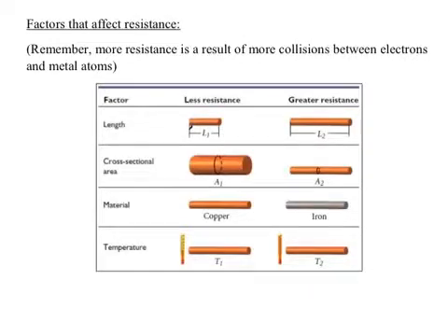It's like having 4 pipe drains coming into one in your house. You'd want the big pipe drain running out to the ground and all the other pipes to be smaller so that when they come together, they can actually flow out. Whereas if you had 10 pipes that are 1 or 2 inches each, and then an exit pipe that was only a 1 inch diameter, it's going to get all backed up. All your water's going to get backed up in your sink and your shower, and it's not going to flow out. So a larger pipe means less resistance.